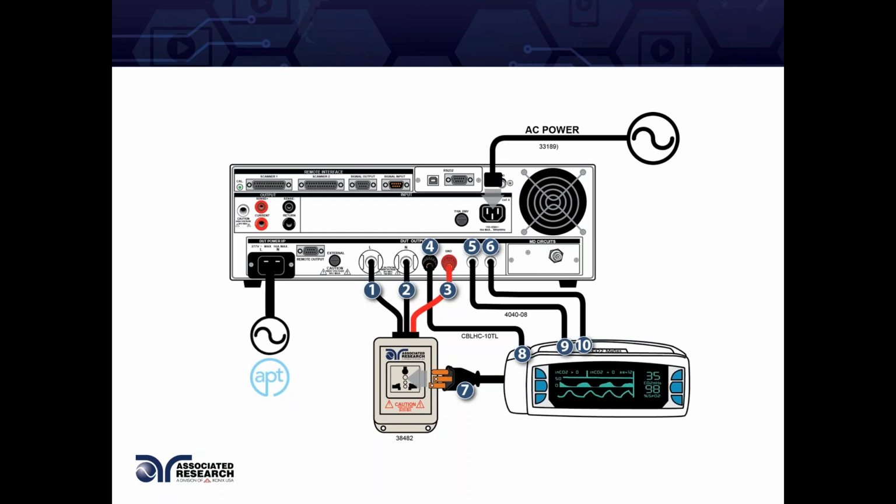The other connections that we see here, the important ones are number 5 and 6. Those are the probe connections, the probe high and probe low. For some special cases of leakage current tests, you are required to measure the leakage current on the surface of the product, like the touch current or the enclosure leakage test that we talked about. In some cases, especially for a medical device, there may be requirements to test some patient connections, or in other words, what we call the applied parts, anything that makes physical contact with the patient.